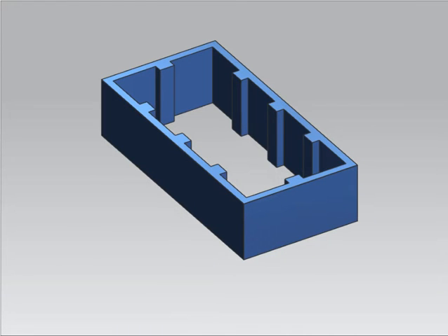This modular building block is a simple example of a highly engineered part. Highly engineered parts are driven by parameters and expressions. The design intent represented by sketch constraints, sketch dimensions, and other equations controls how the part behaves when parameters change. Create these types of parts carefully using expressions, fully constrained sketches, and sound associative practices.